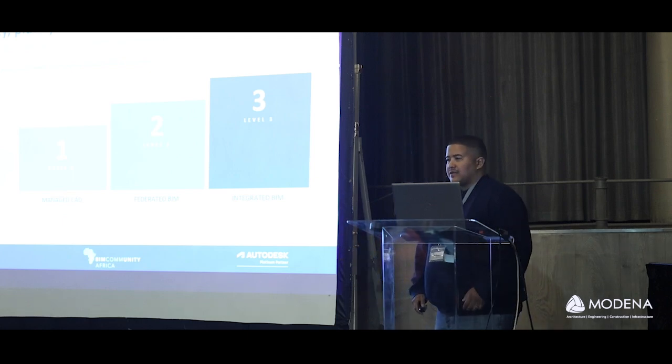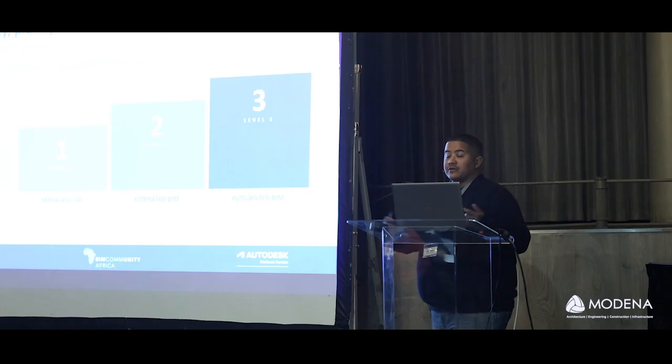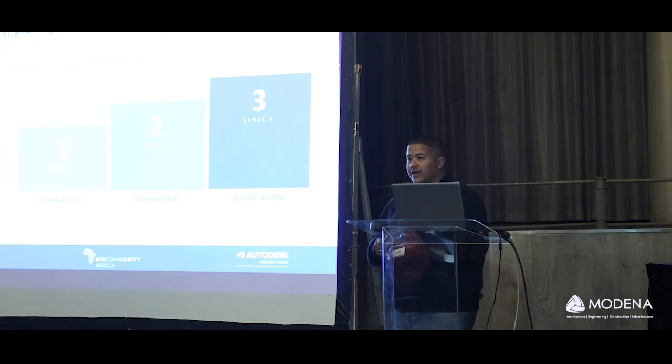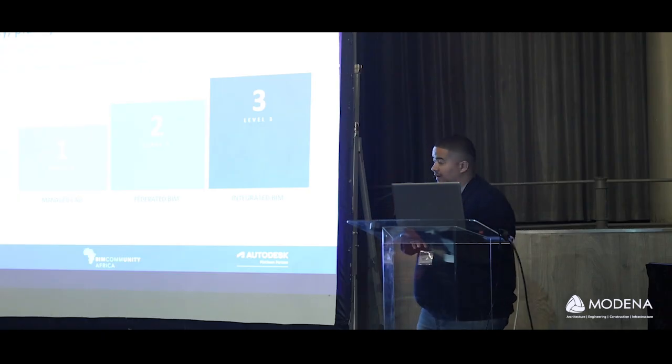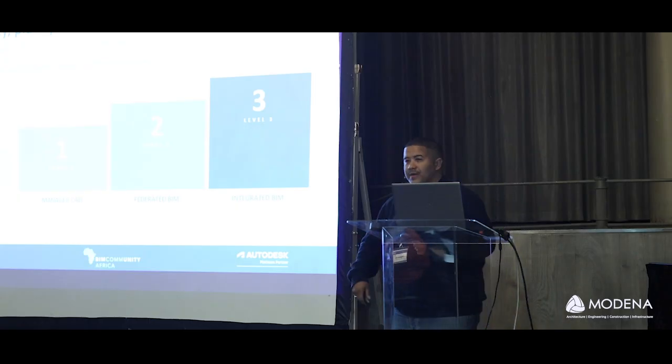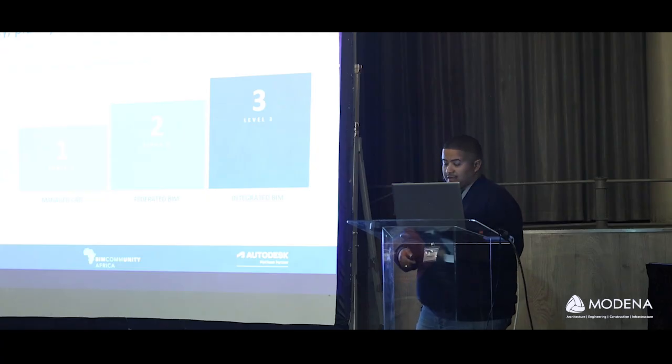It's basically a digital rehearsal. Because everyone is working with their own models, we get to overlay the information in one common data environment, a CDE. And thereafter, as Warwick mentioned about the clash detection process, that's automated, and you pick up those issues before getting to site.